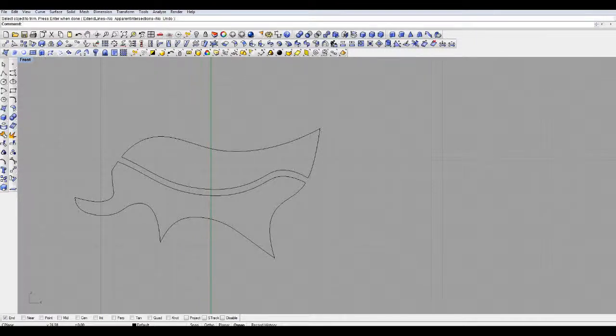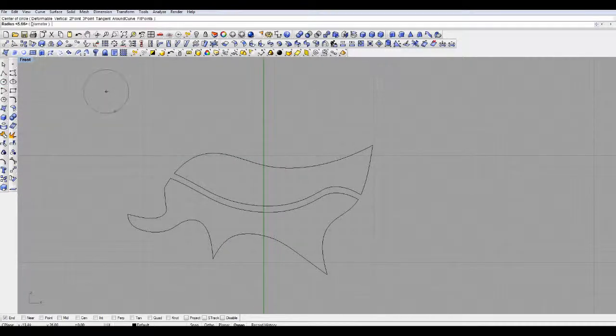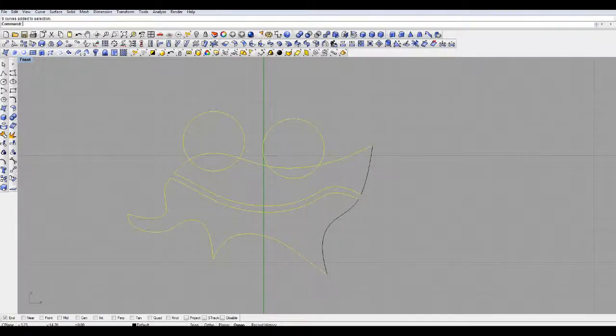Similarly, if you're not just using lines, let's say we wanted to cut out circles from our shape here. If we draw a simple circle like this, and again, the points have to be intersecting, which is why you always want to be working in the same window. If I move this one here, and let's say I copy it like this, and select all. You don't have to select these ones if you're only cutting up here. Basically, all that really matters is just selecting the main curve and the ones you're subtracting it from.